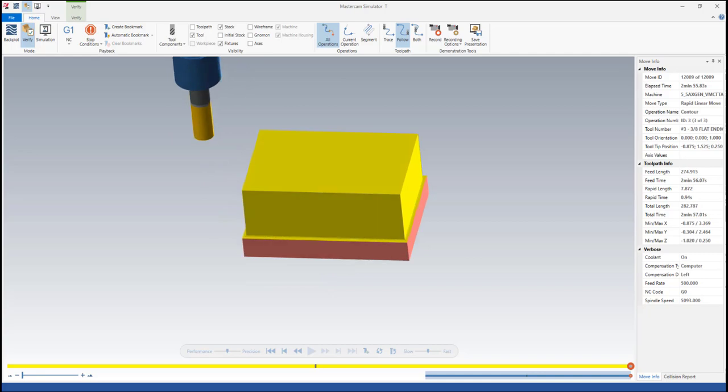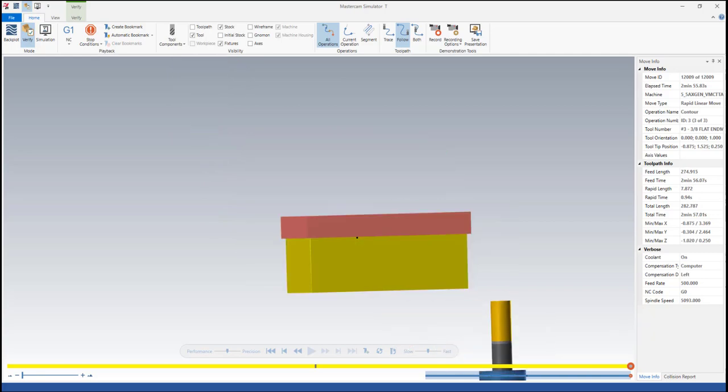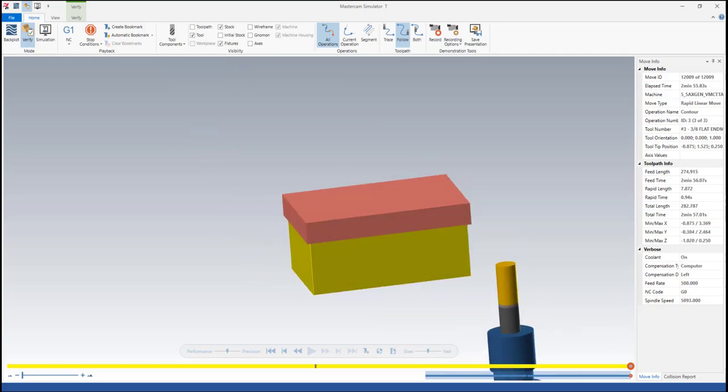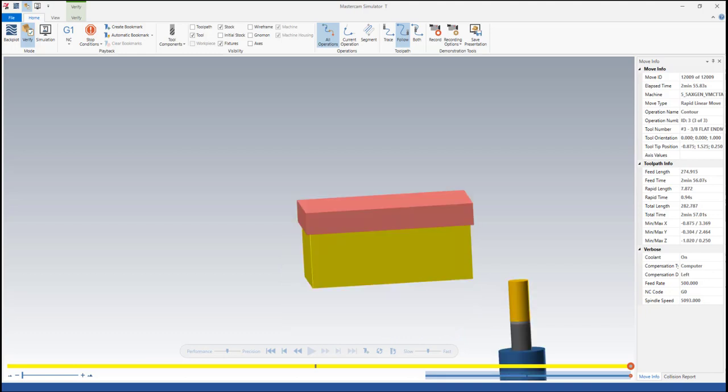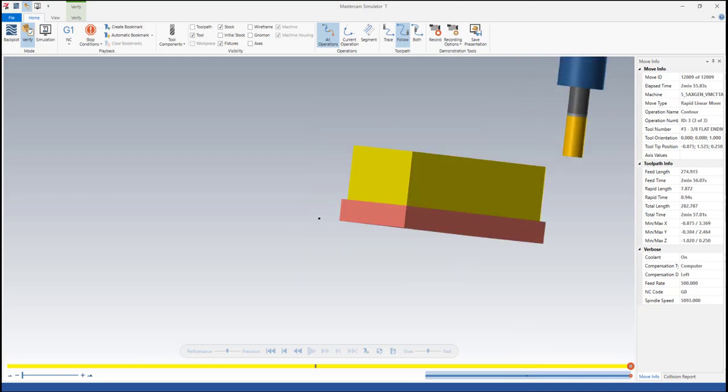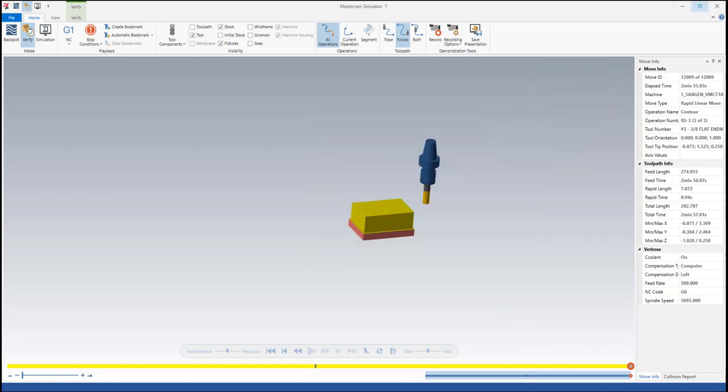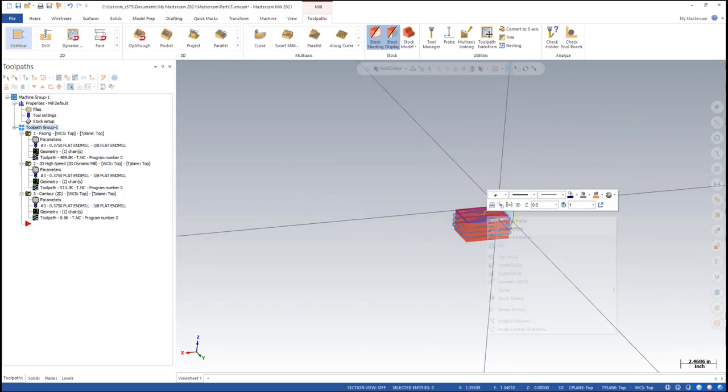And then for op 2, we'd flip it over, put it back in the vise like this, and then we'll just face that off, and we'll get our, this is already defining a flat surface that is perpendicular to these planes. And this plane is 3 inches long, and then this one is 2 inches long. And then all we have to do is flip it over and machine this off, and just go down enough to give us our 1 inch that we're looking for, and then we'll have our finished 3-2-1 block.